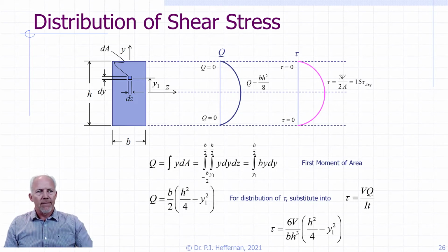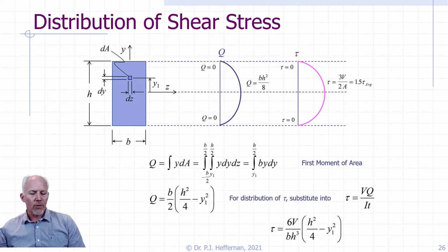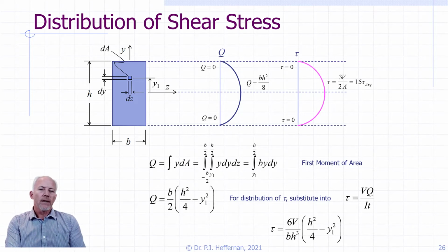The actual values here are less important. They'll be more important when we're actually calculating them out. But it becomes really, really important, because when you're considering where to calculate your shear stress, you typically want to calculate it where it is a maximum. So you have to figure out where in the beam the shear forces are likely to be a maximum, and then you have to figure out where in the cross-section the shear stresses are going to be a maximum, and that answer is in this diagram, which tells you that it's going to be a maximum at the neutral axis. You may also be interested in it at other points, particularly if you have to design a connection, for example, a weld between a flange and a web, or something like that.